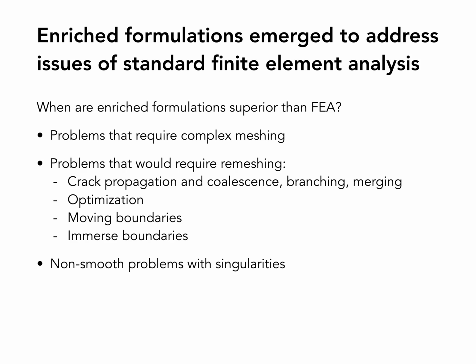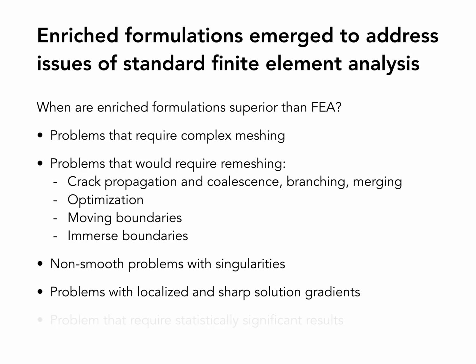If it is not useful, then the coefficients that multiply those functions are going to be equal to 0 after the solution. That means those functions are really not needed to improve the error. Okay, so in enriched finite element formulations, you can add pretty much anything you want to the formulation, and you can also see their behavior in singular problems, which is remarkable. And then problems with localized and sharp solution gradients, and I will show you an example of this in a minute.